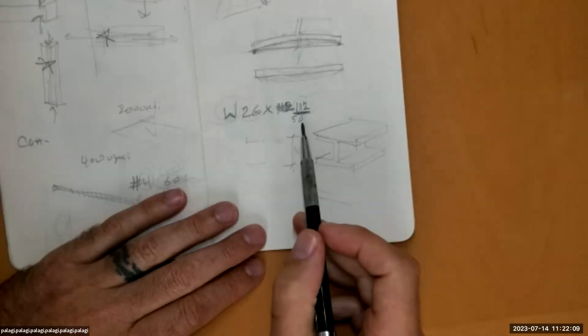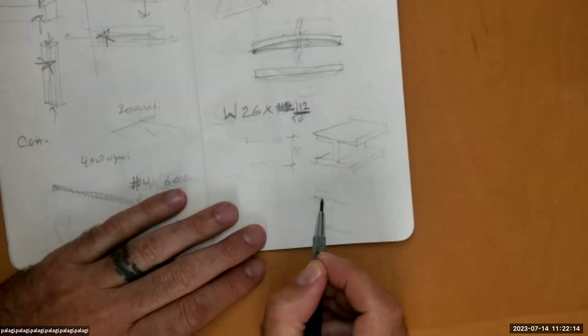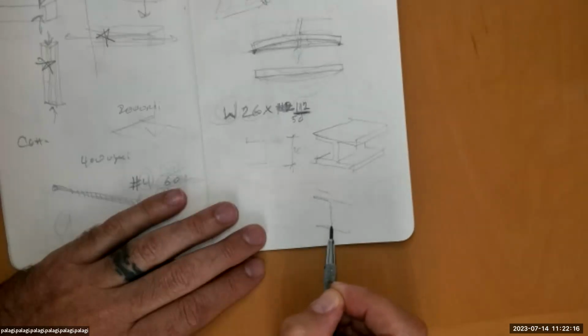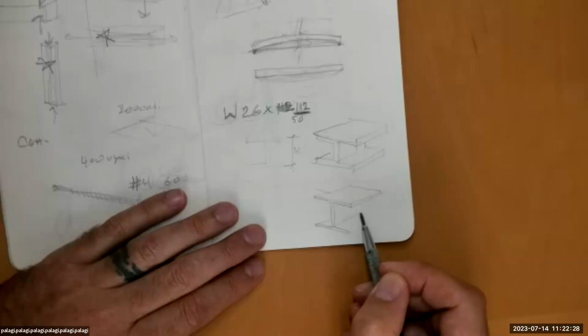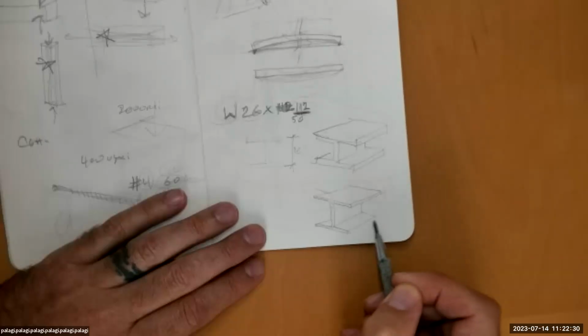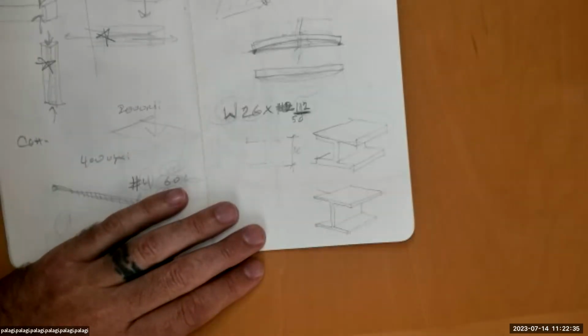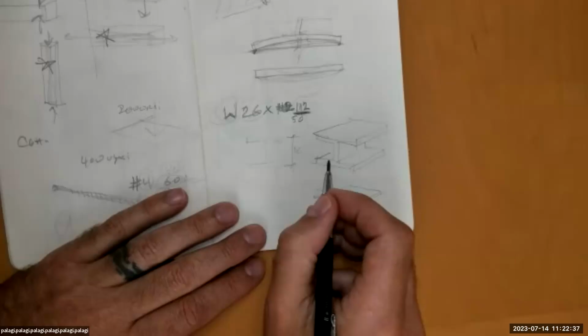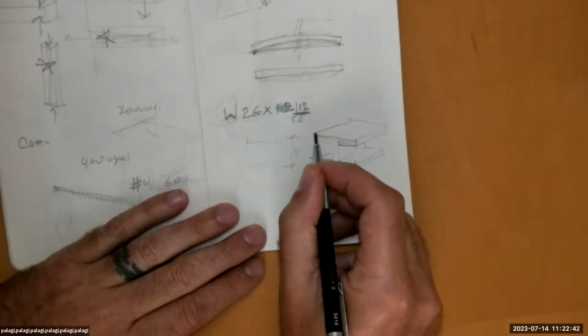If this is pounds per linear foot and we just cut the weight in half, what has to get thinner? Interestingly, we don't label the thickness of the flange as a dimension. It's not part of the nomenclature, but the weight is. So if we know it's a big, heavy one, we know this thing has gotten really thick, because that's how it's getting the weight.